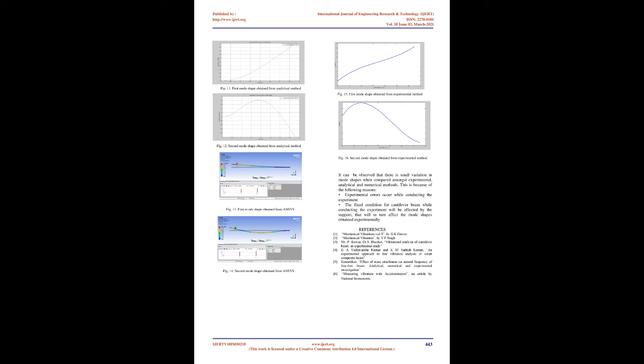X represents the nodal distances to be plotted along the x-axis. Y2 represents the acceleration values of all rows, the 14 nodes, at the second column, or the second natural frequency. The 3 in the third line represents the order of the equation to which the polyfit function is subjected. Since the interpolation model of a cantilever beam is a third-degree polynomial, mode shapes also occur as a third-degree polynomial curve. So, the polyfit function for a third-degree polynomial equation is used.